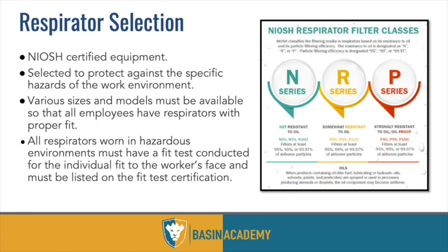So you have to check the SDSs and then verify that with the marking on the respirator or the purchase documents of the respirator to make sure it's the right type for you. Makes it easy in oil and gas, specifically H2S. Scott, MSA, and 3M, as well as Draeger and a few others, have kind of the standard package that's good for oil and gas, is resistant to grease and oil, and then will protect you from H2S, which is the full face piece